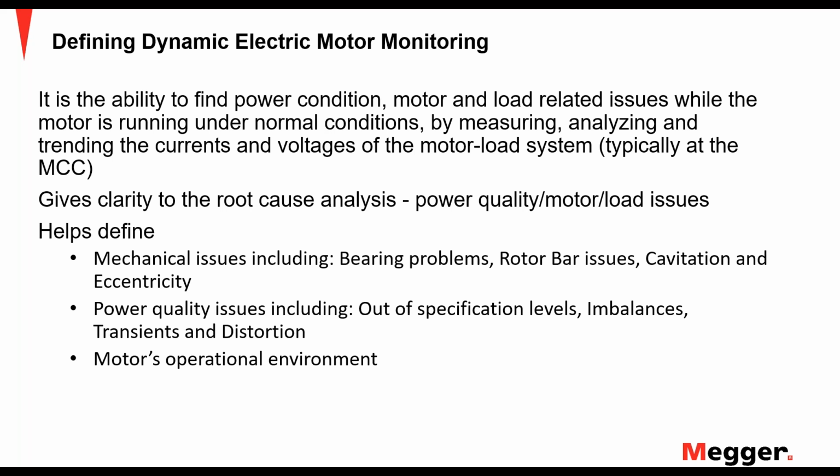It helps us define mechanical issues such as bearing problems, rotor bar issues, cavitation, eccentricity, and power quality issues including out of spec levels, imbalances, transients, and distortion. And then of course, it also helps us define the motor's operational environment. How is that motor reacting to what we're requesting of it by the load, by the power that we're giving it in its situation? We're getting its operational environment.